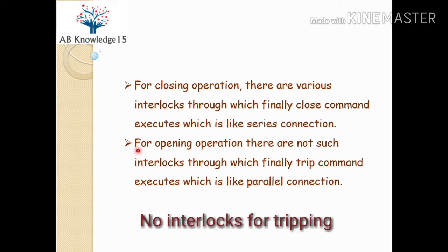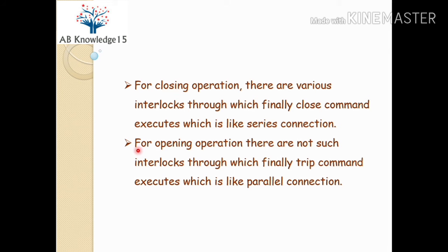If any emergency push button or remote trip is available, then it will also trip the circuit breaker. So there is not any such type of interlocks available for opening or tripping operation of circuit breakers. So that is the main reason why we are getting the closing operation time more than opening operation, and the opening operation time is less than the closing operation of circuit breaker.